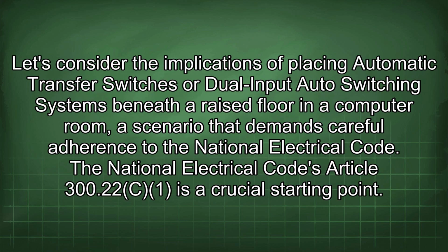Let's consider the implications of placing automatic transfer switches or dual input auto switching systems beneath a raised floor in a computer room, a scenario that demands careful adherence to the National Electrical Code. The National Electrical Code's Article 300.22 is a crucial starting point.